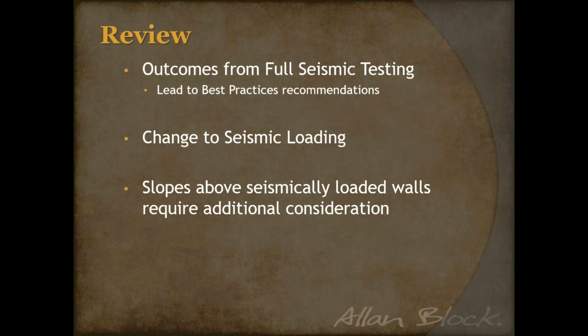Now, when you have a surcharge, we just simply apply the same Mononobe-Okabe equations that we normally do, and we get your active pressure, your surcharge pressure, and your dynamic load, and it all gets added, and it's got to be resisted by your lateral pressure. So great question. Hopefully I answered it that way, but some very insightful questions as we've gone through this.